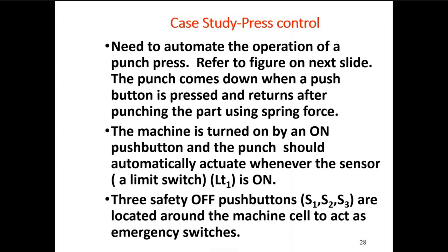So let's look at how I can automate this process using a bunch of sensors, a bunch of outputs, and using a PLC to control the process. Okay. So what should I identify? Like before, decide what the inputs and outputs are that you want to use on this process. The example I am going to use for the die works like this. When the hydraulic force is sent to the piston, it comes down to press on the part and then automatically returns home when it has fully pressed the part.